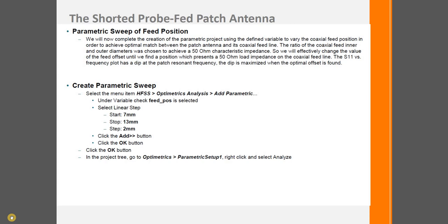Then click add, and we can go into the project tree, and in the Optimetrics window, using the parametric setup one, right click on it and select analyze.